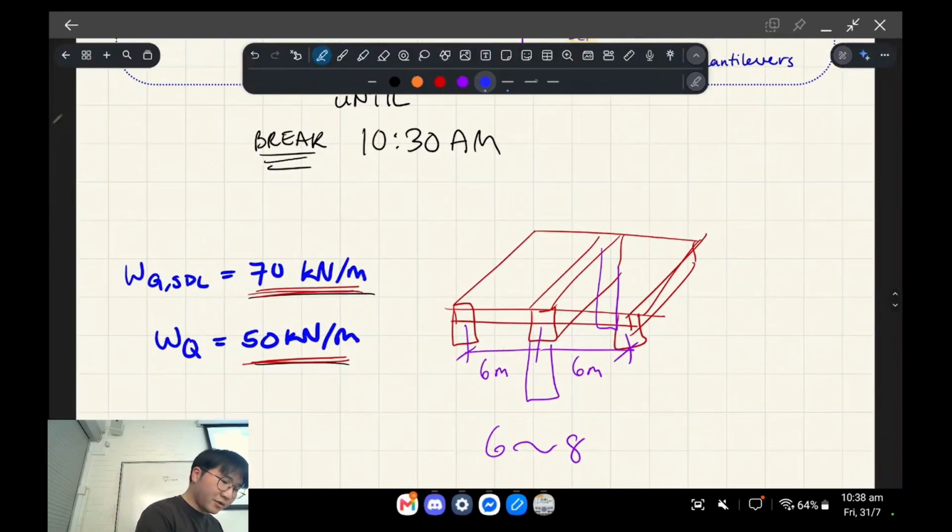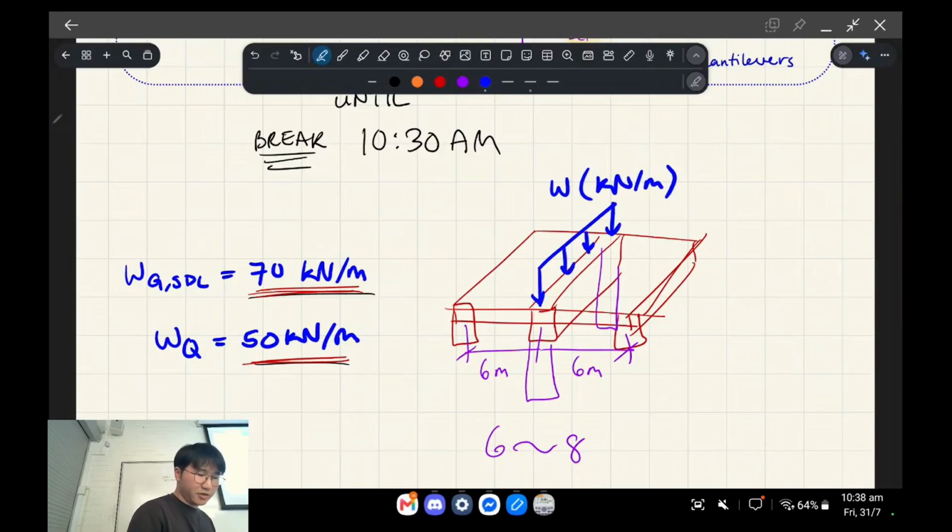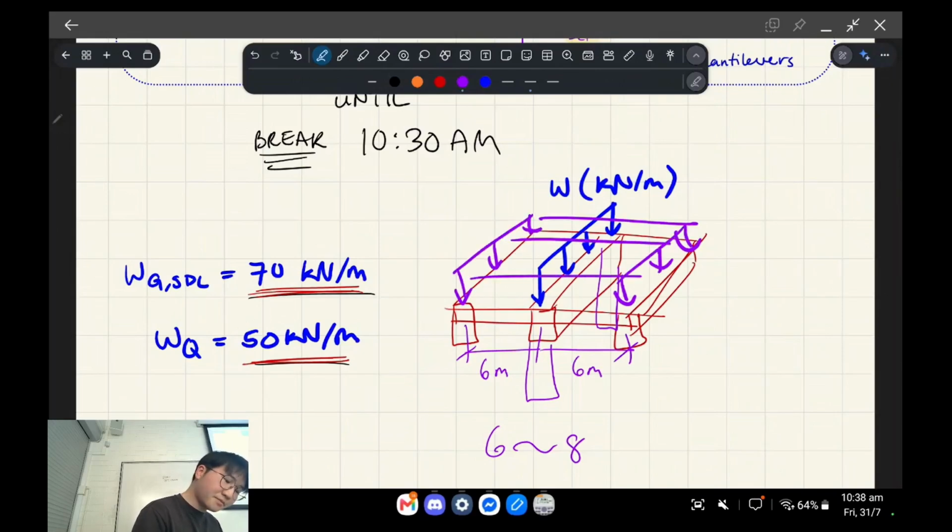And so they're giving us this load, which is the linear load, W in terms of kilonewtons per meter. What's the kPa load, what was the load when it was a pressure value? We got that through, let's call it Q, instead of W. Q was W multiplied by that center-to-center spacing.